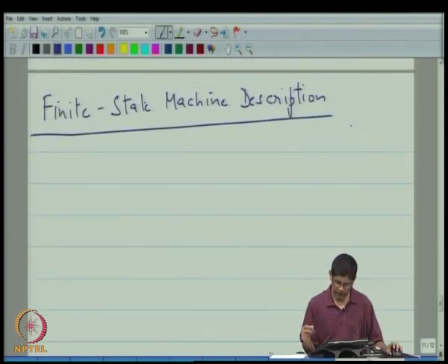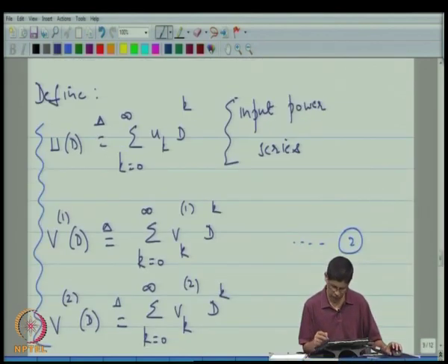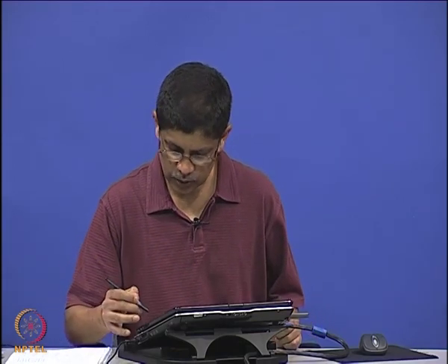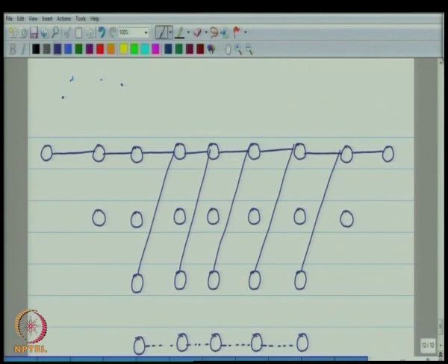So, the finite state machine, of course, is a reference to the encoder. You see that the encoder has 2 shift registers, and since each shift register can store either the value 0 or 1, in a sense this finite state machine has a memory of 4, or in other words it has 4 states. So, we are going to write down these 4 states here.